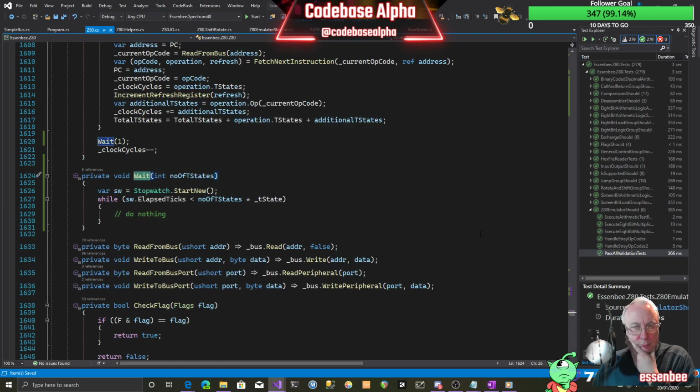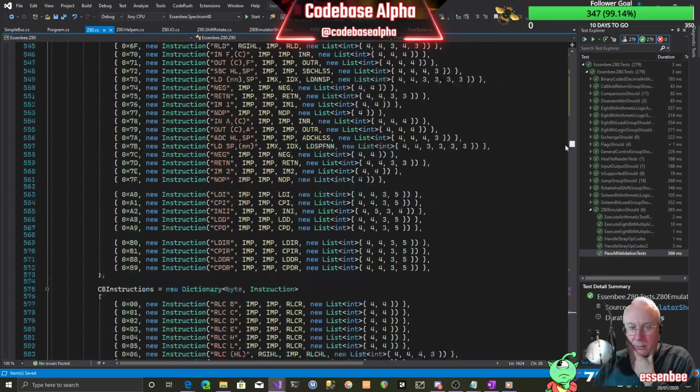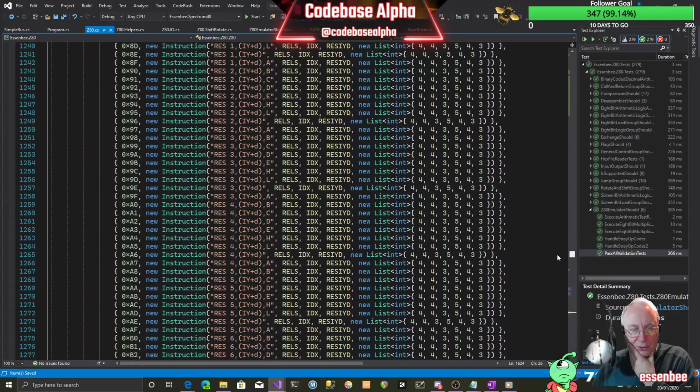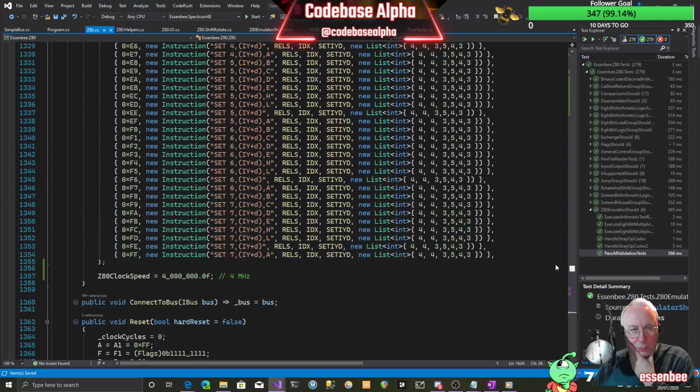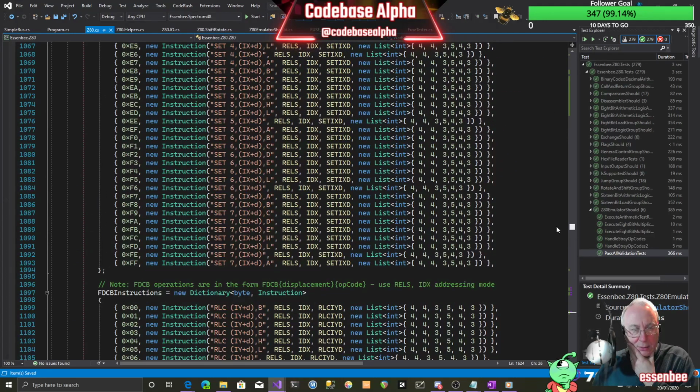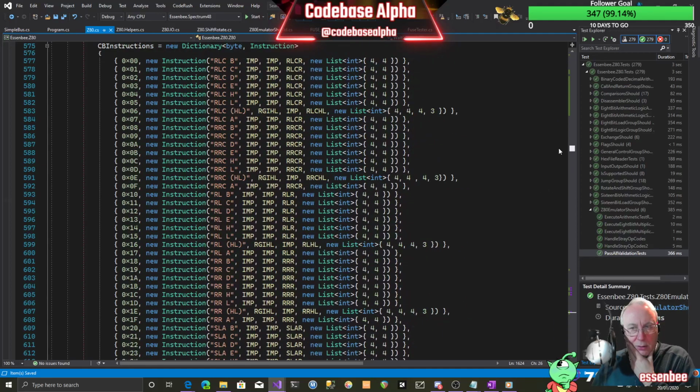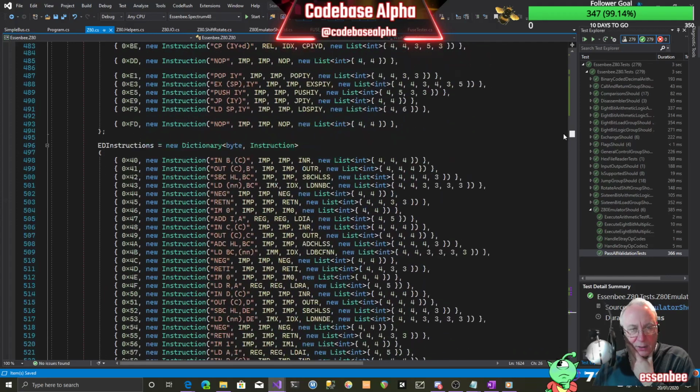So this is where, for Dock in a Frock, we can see how all this works. There are these huge instruction tables, and this is an ED command, I believe, so we need to find the ED instruction table. Unlike a simpler processor like the 6502, which had single byte instructions and therefore a maximum of 256 instructions, the Z80 had a lot more because it had multi-byte instructions, and the way it works is reasonably complex.